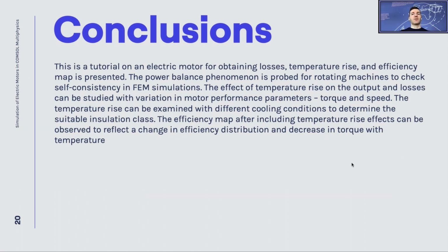And we can also use the built-in geometry parts, the part library. So we can easily create parametric geometries. So we can fine tune our very first electric motor design to our needs. What could be the maximum allowed temperature? Do we need active cooling or is a passive one enough? What should be the maximum allowable driving current and so on? So you can create very nice and robust electric motor calculations here.